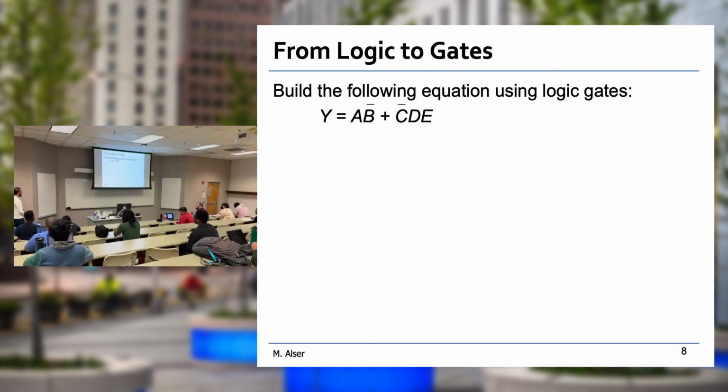Okay? So this one uses a 3-input gate, and this one uses 2-input gates only. So it's up to the question. Sometimes we don't have these 3-input gates. We only have 2-input gates, so we cannot use this one. So consider everything here canceled, including this wire, and then you can consider this view to replace this 3-input gate. All right? And then the OR, because this is sum of product, we end up having an OR gate at the output. Right? That's excellent.